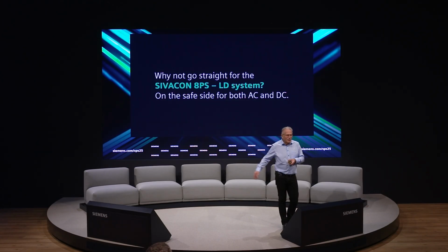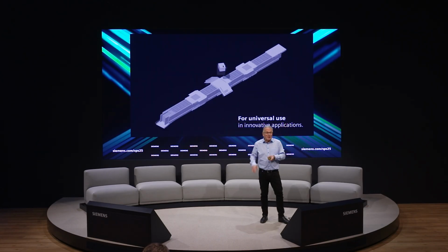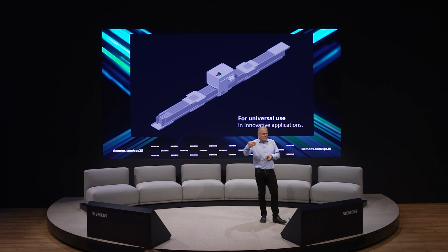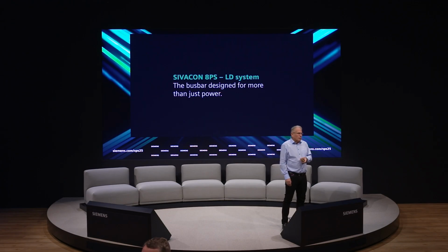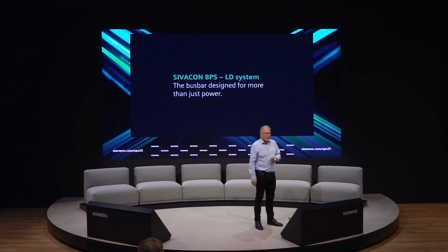So let's talk about AC/DC. Today morning we already had some music fitting to this. No, let's talk about direct current, DC. DC is becoming more and more interesting as alternative to many applications. And here we have with our busbar trunking system a major advantage because of our air-insulated system. We have an air-insulated system which fits perfectly to direct current. And with the LD system, it's a high current busbar trunking system, we adapted it very, very early to be used in direct current applications.